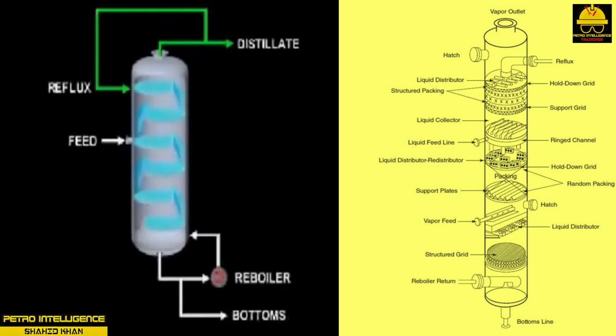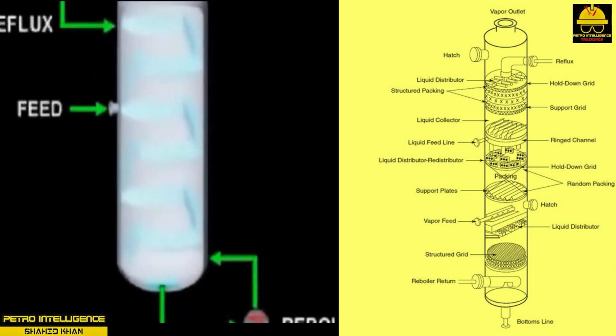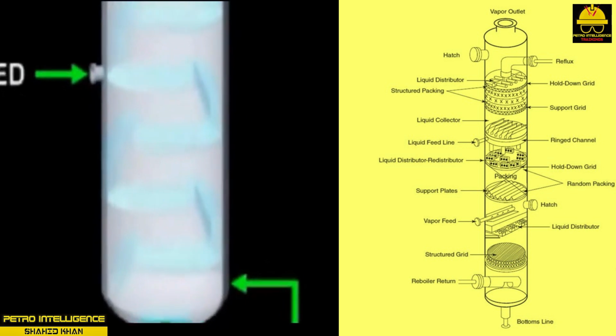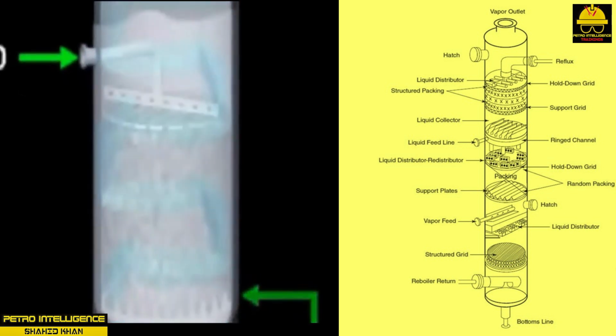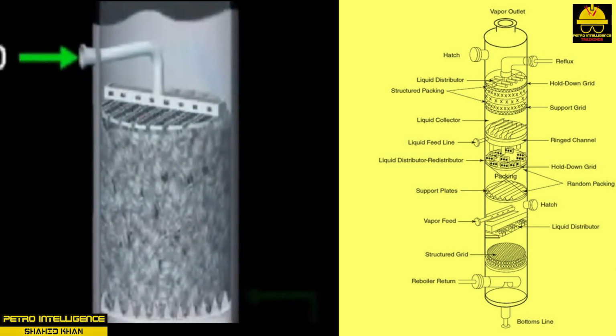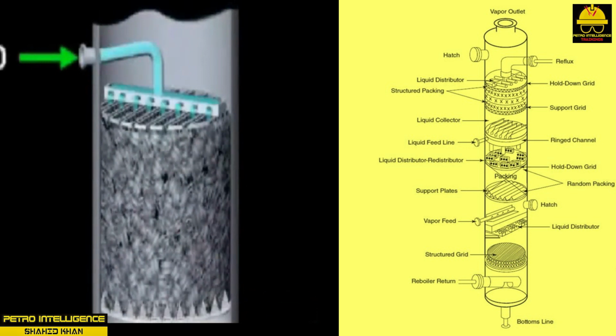There are 3 types of packed distillation columns: random, structured, and stacked. Random packing includes discrete pieces of packing that are randomly dumped or poured into a packed column. Packing provides a surface for good vapor-liquid contact, distillation efficiency characteristics, and predictable pressure drop.